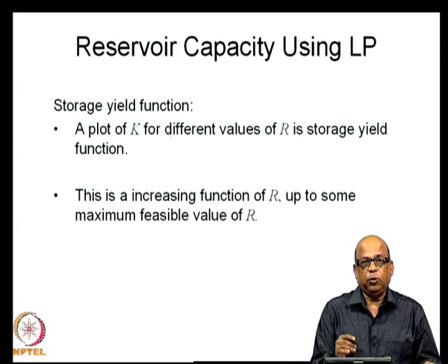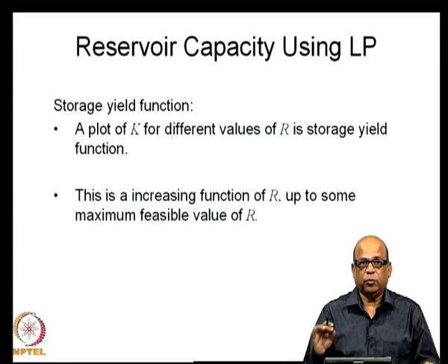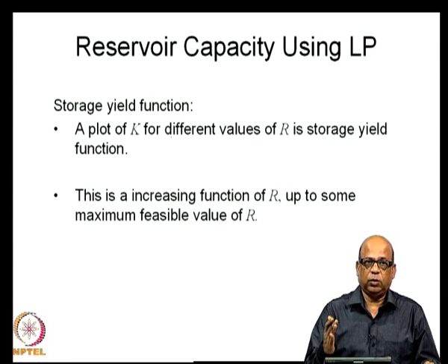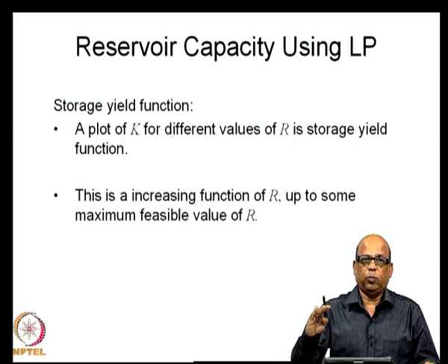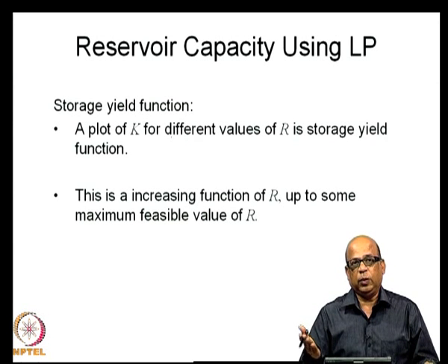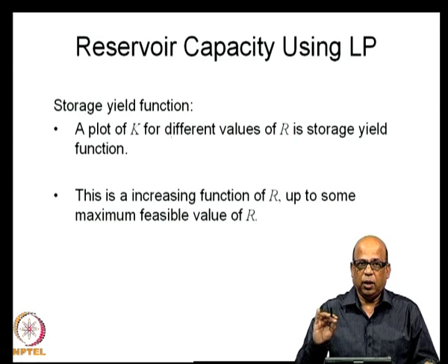So, we need to develop a function which relates K versus R, that is for a given capacity what is the yield. So, this is the storage yield function, that is what we do, and as I said, it can only go up to a certain point, beyond which it may remain constant, which means no matter how high you build the dam, how large is the capacity of the reservoir, there is only a maximum limit up to which you can meet the demands, and that will be limited by the inflows. So, it is called as flow limitation.